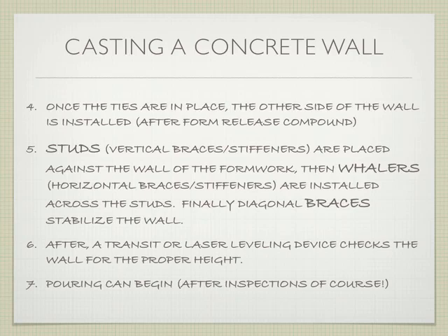And obviously, if you're in the middle of the pour and the bottom of your formwork blows out, all the concrete comes out and it's a giant mess. Furthermore, the concrete's now in contact with the dirt, which mixes into the concrete and lowers its strength. Basically, it's a big problem. So you really want to be careful about how high you pour in one wall and make sure the formwork can withstand it. Generally, 1 story is about the max that people try to do. So after you've leveled the top of the wall, you can then begin pouring.